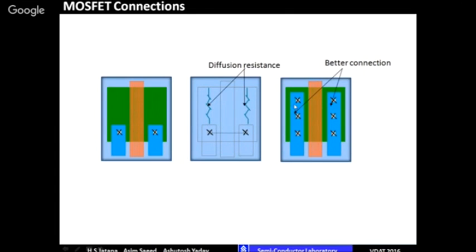So what you have to do is, if you put one contact with a resistance of say 10 ohms, so you have put 3. So what will be the contact resistance of 3 contacts? The 3 are coming in parallel. So you have reduced the contact resistance. Whereas if you do it here, there will be 10 ohms of this contact, and this area will also lead to some resistance. So this resistance will directly come in drain or source. That will affect. Okay, diffusion resistance will come. So this is a better layout.